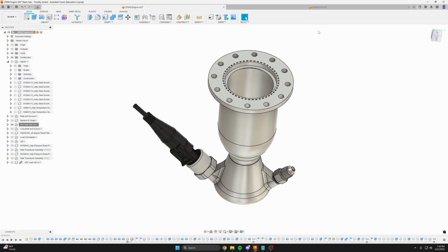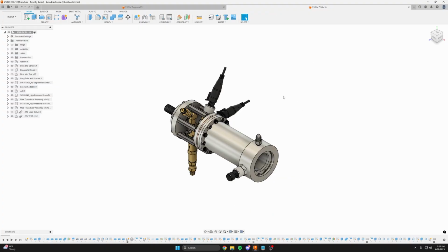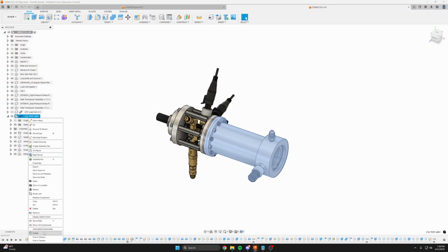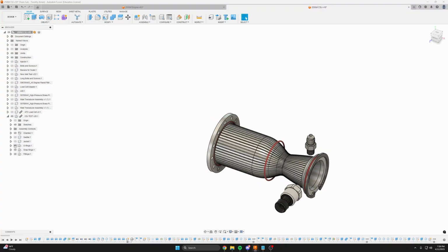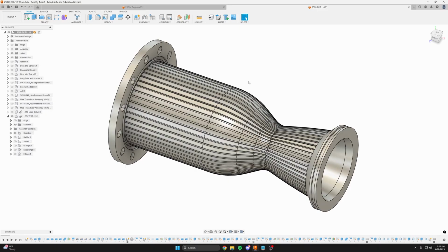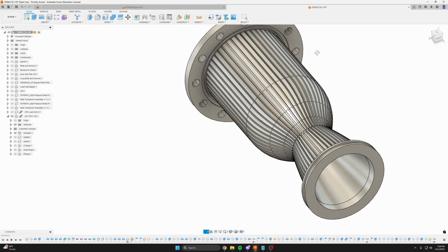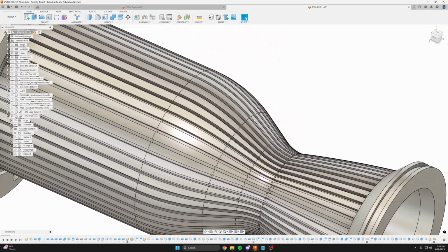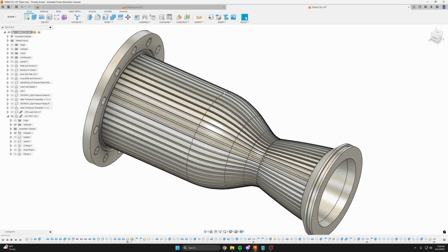Another option is to use what's called a chamber saddle jacket design, a CSJ. This is what we've all pivoted to recently for that reason and other reasons. I guess I can't isolate this. So if you see this chamber, this is the metal printed part, and now the slot channels are open. They're open face, so there's no space for the powder to get trapped in this design.